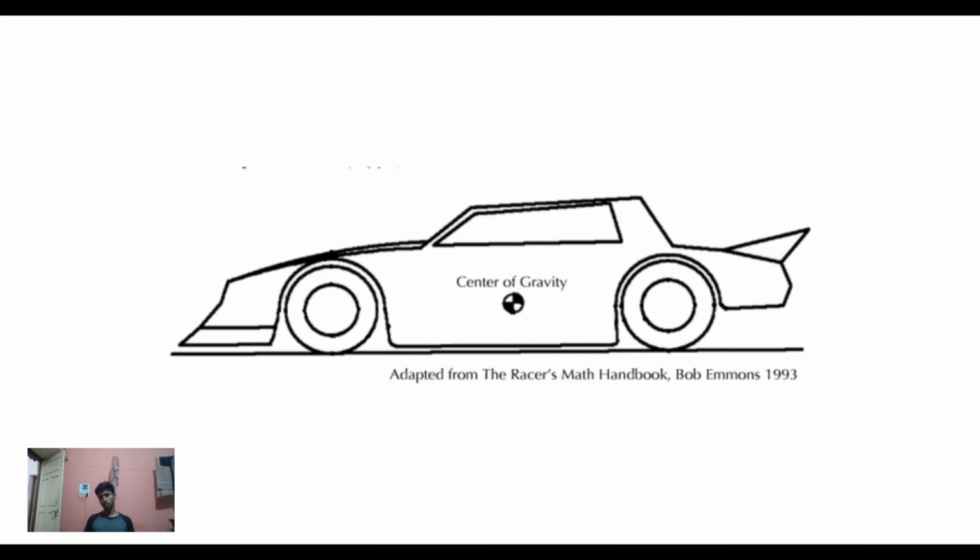So the CG height is lowered because that leads to a more stable configuration. And in terms of the lateral position, the CG is usually located at a distance which is half the wheelbase. That is the point where the normal reactions acting on all four tires are equal, and this leads to the most stable car.